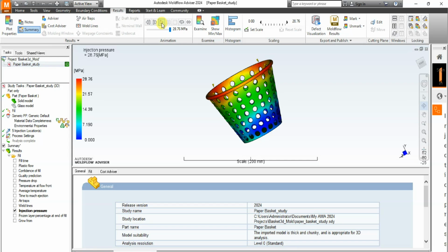Furthermore, you should also know that if changing the gate location to lower injection pressure is not possible, you can redesign the part to increase the wall thickness. This seems to be a general solution to most of these problems that have to do with short shots, hesitation and other production issues.